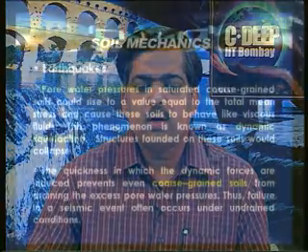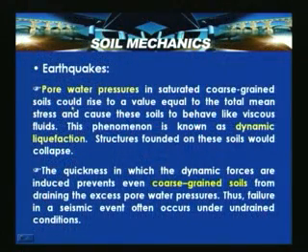While discussing earthquakes, one major phenomenon we should discuss which happens is called dynamic liquefaction. Here pore water pressure in saturated coarse grained soils could rise to a value equal to the total mean stress. That is, the pore water pressure will increase up to whatever the total stress is at a particular point, and cause these soils to behave like a viscous fluid.